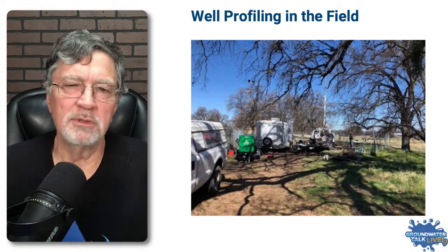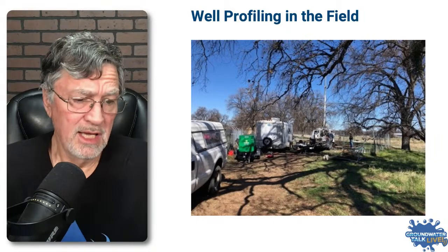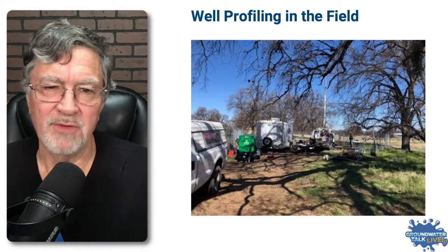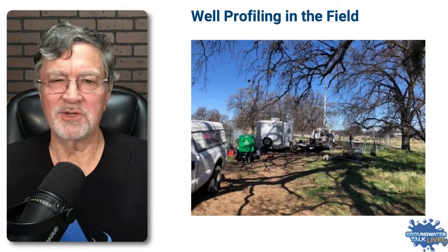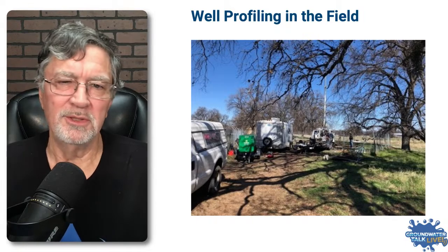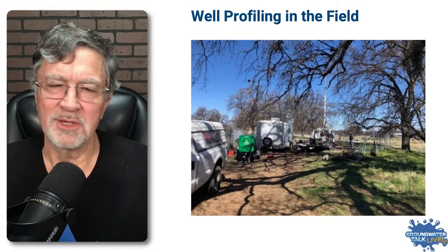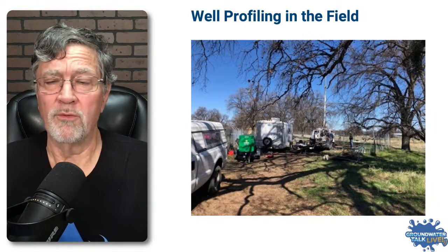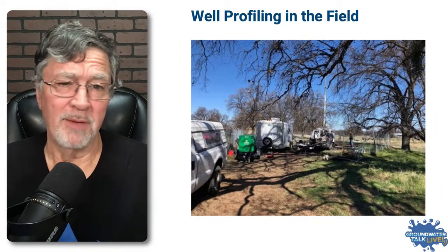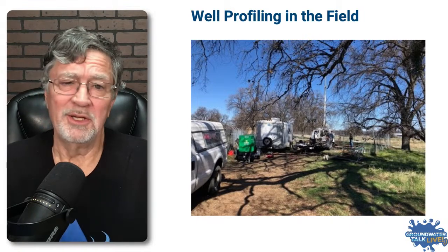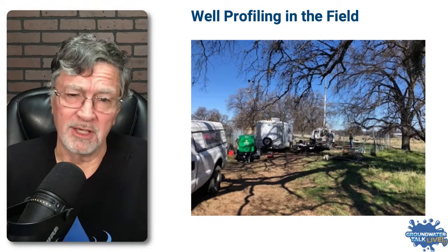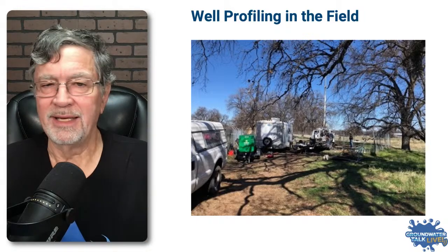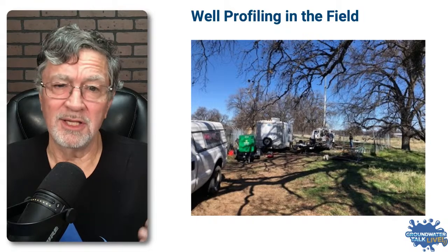We were able to define some specific zones, and in this case, we were doing things up front as part of a well design. So we actually designed the well to preclude the bad water, the contaminants, and that's another case for well profiling right up front when you're doing your test well, is to actually design the well up front. But we can go in and do this retroactively as well, and so it's a good technique.